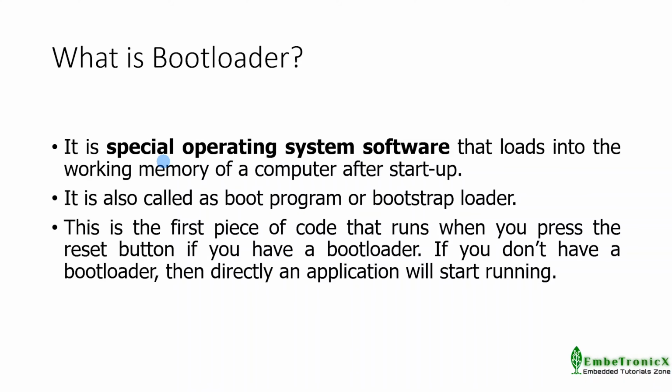What is a bootloader? A bootloader is a special operating system software that does some functions like hardware initialization and loads the actual application. This is also called a boot program or bootstrap loader. When you power up the system, this is the first piece of code that runs. Some systems, like small microcontrollers, don't have a bootloader, so the application will be running directly.